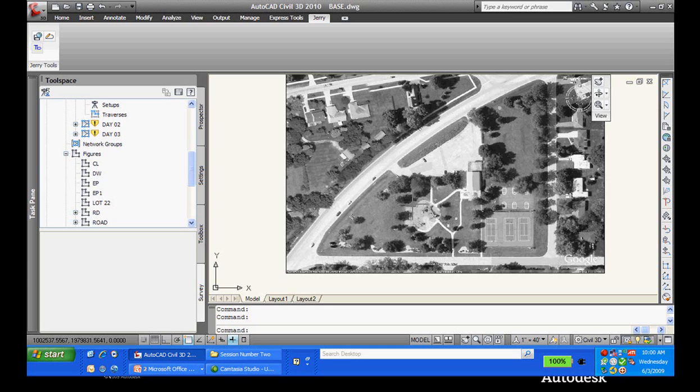When you survey stuff, survey accuracy, that's why we have it surveyed, so that it's the highest level of accuracy possible. Trees. All right. If I'm not going to use the tree location as part of my surface creation, I just want location. We would send guys out, because it was the arborist, they would know all of the Latin names for all these trees. We'd send them out with a handheld collector that's got sub-foot, now in some cases even sub-8 inches accuracy. We'd let them collect the trees themselves, all right? We'd set the values so they couldn't alter their PDOP or anything outside of what we would consider acceptable. Let them collect the trees, they fill in all the attributes that they're looking for.